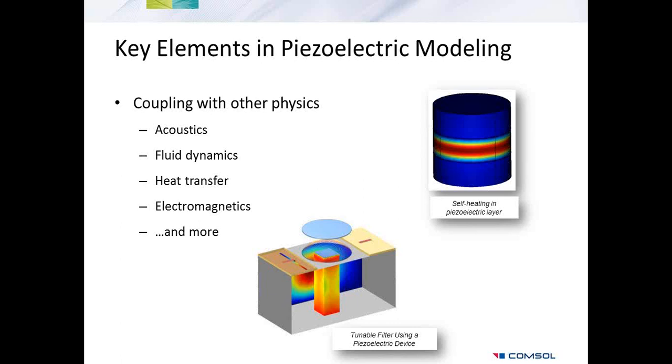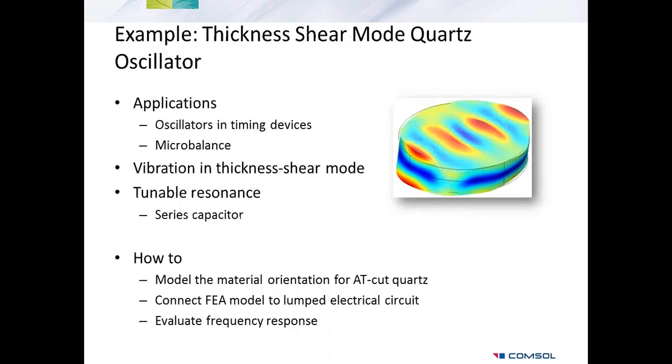Another such multiphysics simulation could include the combination of piezoelectric analysis with a full-wave electromagnetic analysis in an evanescent mode cavity filter. In such a filter, a piezo actuator is used to control the size of a small air gap, which can be used to tune the electromagnetic resonance frequency. Let me go ahead and present a couple of examples in a little more detail.